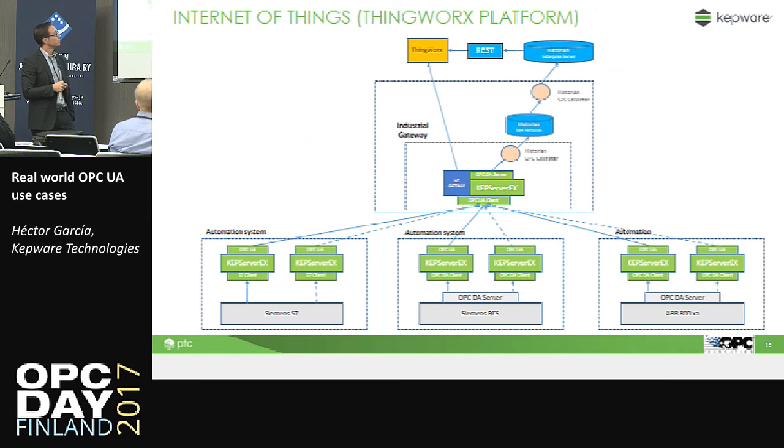And just out of the box, Kepware EX is an OPC DA server, so it was possible to send information to one historian, one instance of GE historian they had for each of the 14 locations. And then they had a corporate historian, but it has nothing to do with OPC. In this case, they were copying everything in this corporate historian.